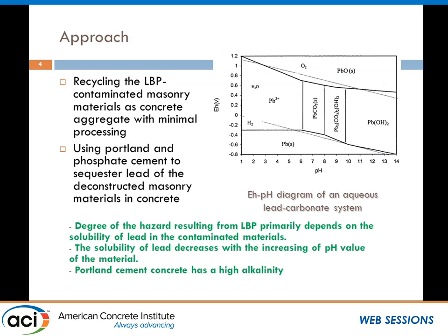Approach. So the idea is actually fairly simple. We want to use the high pH environment of concrete. If you look at this chart, you can see that the lead leachability really depends on the pH. And for those of you familiar with concrete, our pH is right here. That tells you the leachability of lead is really low.